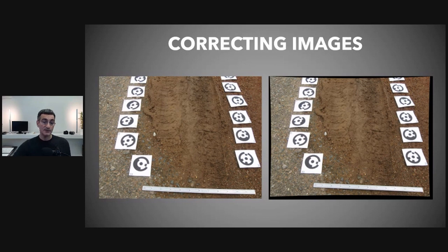And in fact, if you look at the image on the right, you'll notice that there's a little bit of a black border, and that black border is not even. It's larger on one side than the other, larger on the right side than the left, and larger on the bottom than the top. You'll also notice that it's tucked in. There's a little bit of curvature there. So it's bringing in the image so that any curvature that it introduces, it's going to remove. And so that's an optimized, or in Photomodeler, for example, they call that an idealized image.